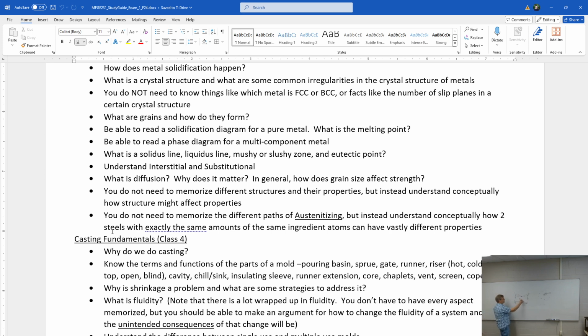Down here is all solid. All up here is all liquid. And remember, these sections on the end are the solid solutions. So the material is all solid in these, but it is a mixture of the two materials where you can't tell them apart. They're completely in a solvent-solute state, a solution. It's hard to describe a solution without saying solution.